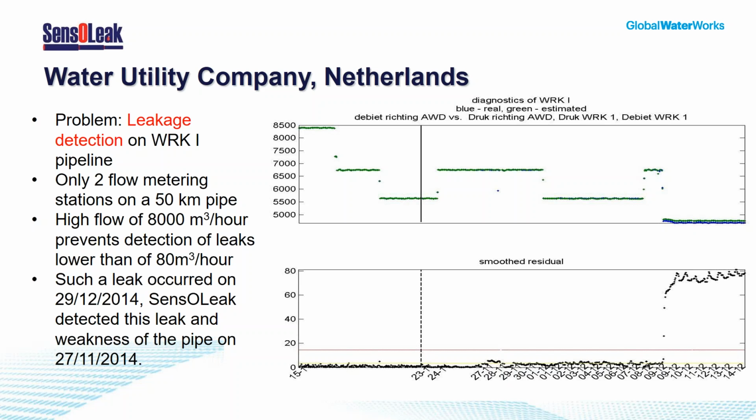So it's 2017, I would ask for a case from 2 or 3 years ago, and we request 2 sets of data. One set of data should contain 3 months of normal behavior or as close to normal as possible, meaning data that does not contain leaks, because this is for training. When we train the algorithm to recognize what's normal and it contains a leak, it will learn to recognize leakage as normality, which is not.